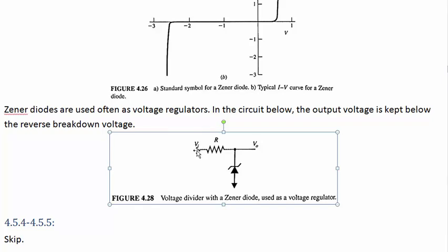But if VI is greater than the reverse bias breakdown, let's suppose VI is a little bit unstable. Suppose this is 7 volts and the reverse bias breakdown is 4. Then we'll get 3 dropped across here, at least 4 volts here, so it'll put out any current. Now what happens if this raises up from 7 to 8? Then the voltage here can't rise because that would mean an infinitely large current going through here, and as soon as that current tries to go up, it'll raise the voltage across the resistor. So instead, all of that just appears across the resistor.